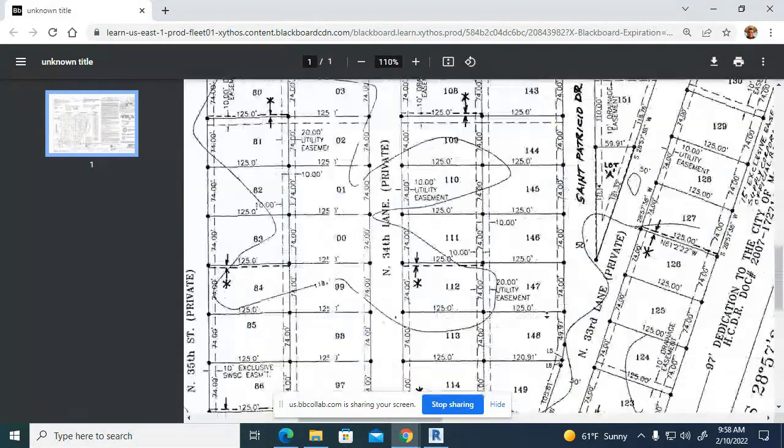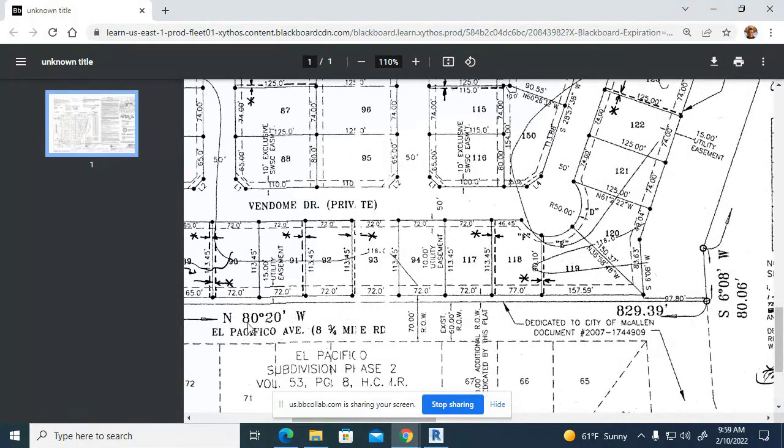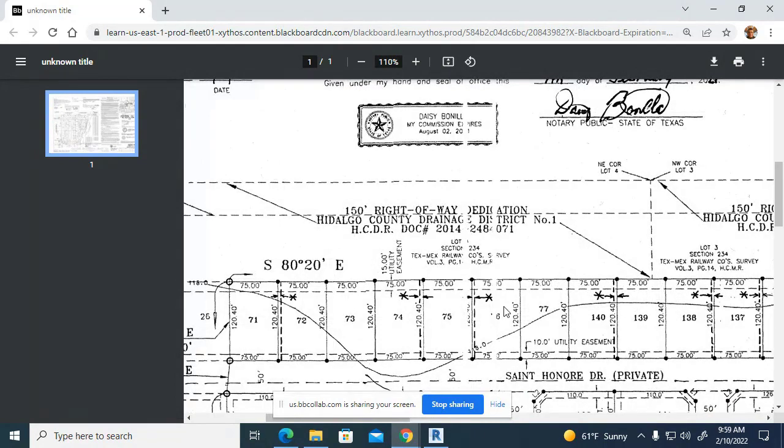Okay, let's move down to the bottom of the subdivision. Oh, here's the bearing. Nope, that's a distance. Oh, here's a bearing. Usually these lines get offset when they're creating these subdivisions, so it's always perpendicular to the boundary. So here's our bearing: North, 80 degrees, 20 minutes west. What's the top one? Should be one on the top right there. Oh, yeah, but it's opposite. I told you I'm starting at the bottom and going around this way.